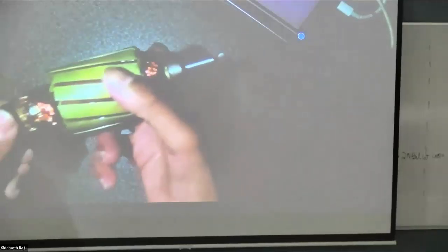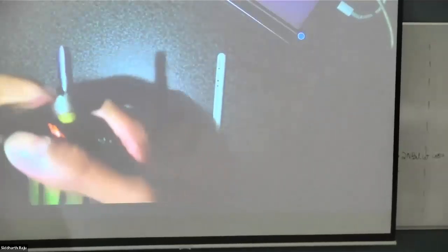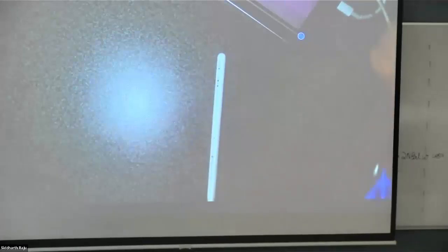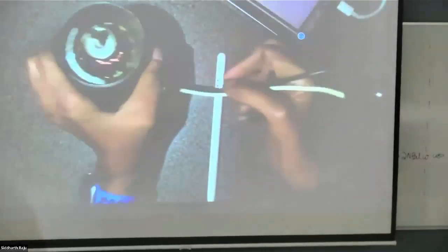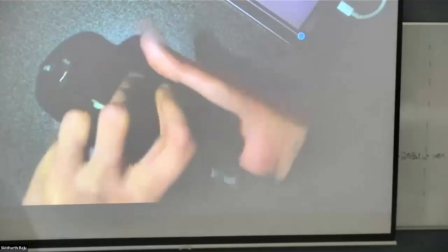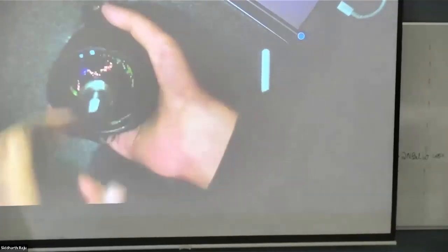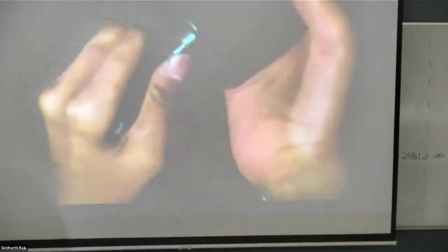And then this whole rotor structure, we put some bearing, and this whole thing goes inside this motor, with the commutator going this way. Then we put some faceplate, cover both sides, and that's about it. Typically with high power motors, you would have bearing on both sides because the motor is bigger. But in this case, the motor is thin, not heavy enough, so there's just bearing on one side.